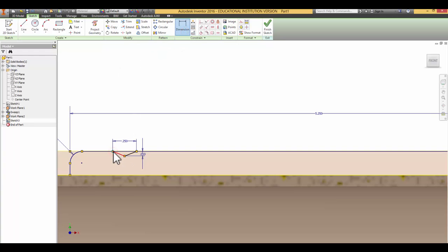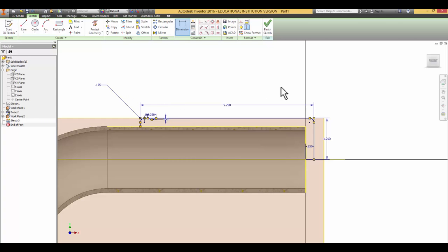I want to go that edge of the V right here to the center point here. I want that to be 1/10 of an inch, 0.1. And so you can see I've got 1/10 of an inch from the center point. I've got my V with equal legs for my triangle here, an isosceles triangle, and the base of that triangle would be 0.25, and the height would be 0.05. And that is all of the sketching that I need to do on this actual portion of the grip.